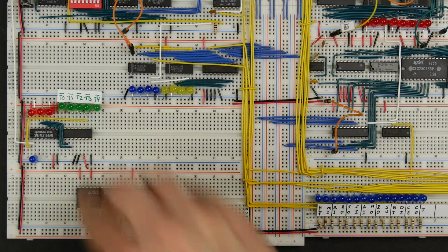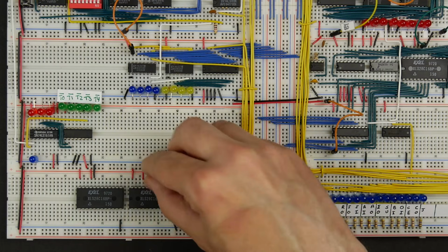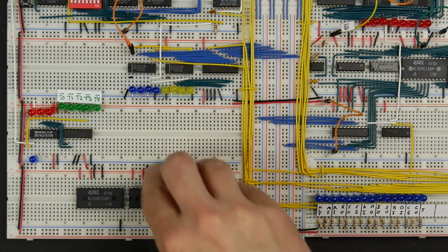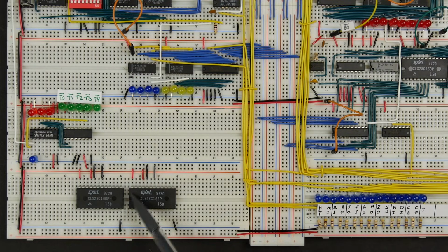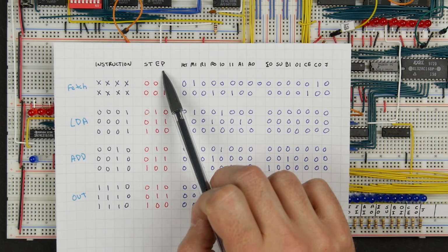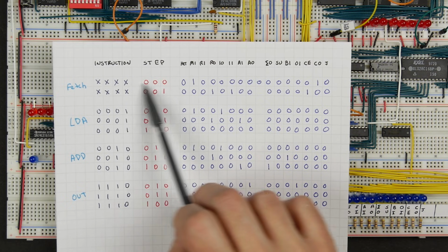So I'll set write enable high on both of these, and then output enable low, so that's active. And then chip enable is also low, so that's also active. Now the address lines for each of these chips is going to come from the instruction as well as the step, because those are kind of the inputs, if you will, to this truth table. So those are going to be the address lines.